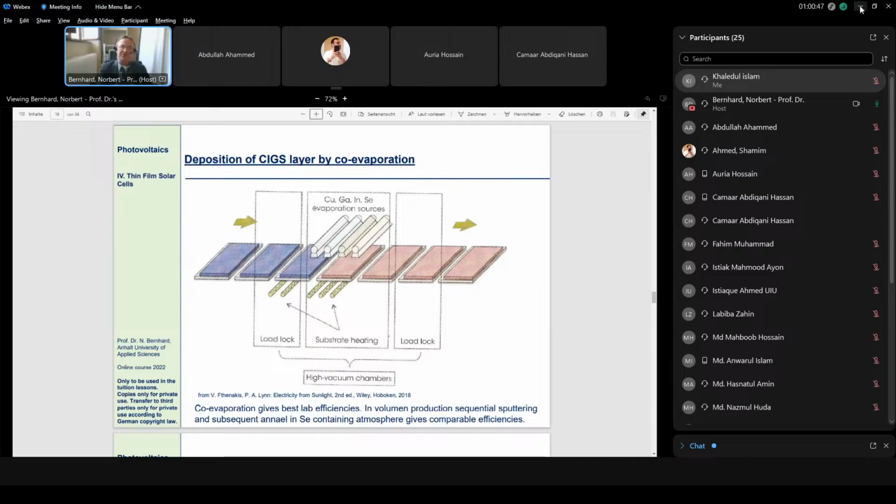Okay, this is a band diagram and working principle of the dye-sensitized cell. The left-hand side is similar to that what we know. We see here the TCO, and here we see the titanium oxide. But here, of course, this is new, and this would be the dye. And usually ruthenium is used, ruthenium embedded in some organic molecule. This is a metal organic substance.